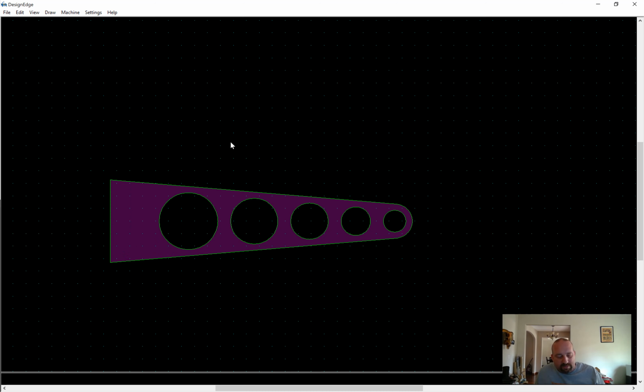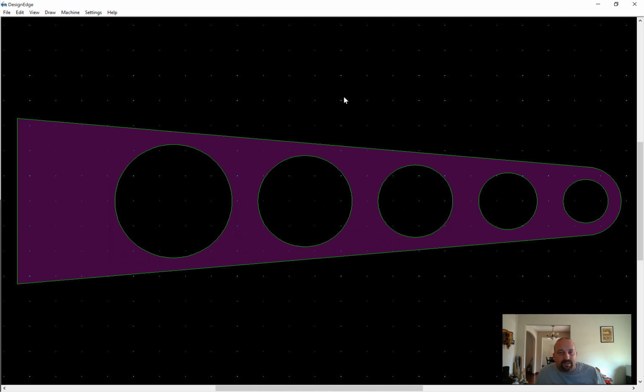So this would be my submission, that the correct way to draw it would be to use the bisection of an angle to find where you need to draw a circle that is tangent to both lines. And I think that will give you the desired result. So hopefully that is helpful, and it's good talking with you.